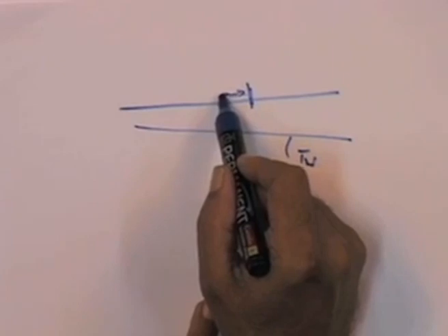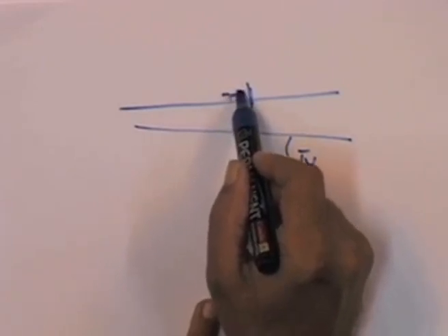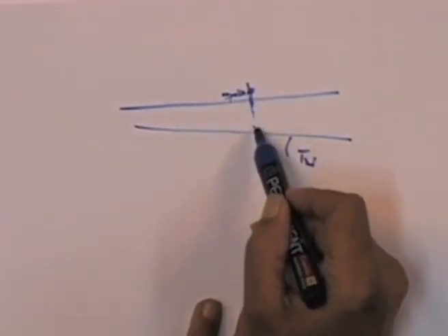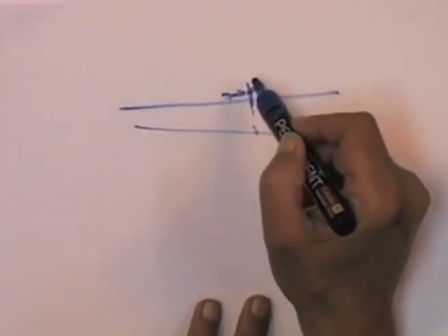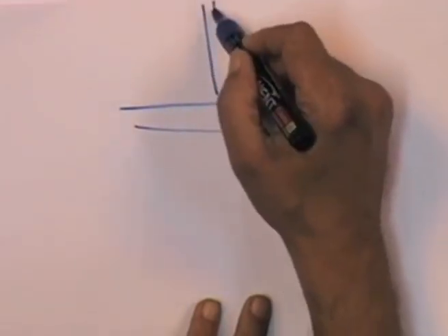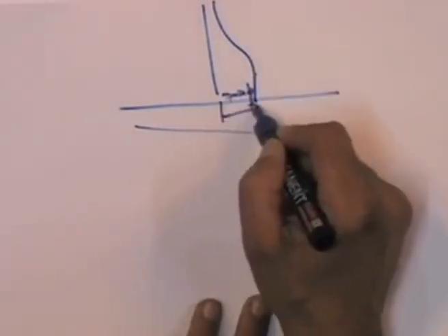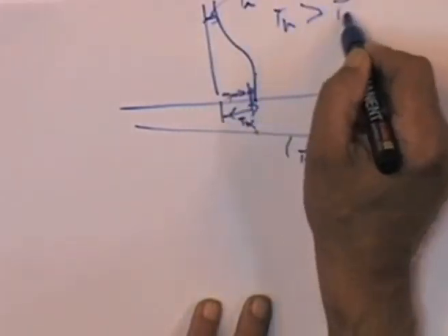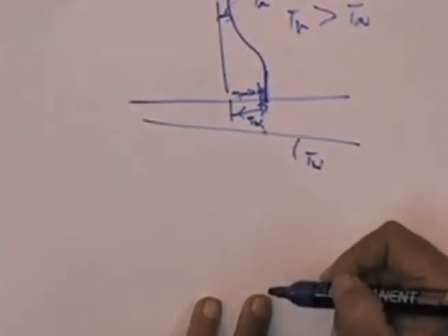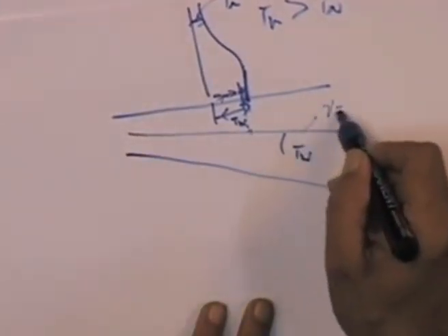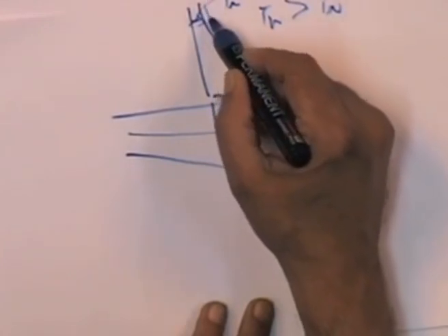much so that the convected heat into the layer, the temperature here could well become absolutely equal to the temperature of the wall at that point. So, in effect I get a situation where I have a profile which will look like that. So, basically although Tw is bigger than T infinity, I could get a situation where it is like that. If the slope is still negative, this corresponds to gamma equal to minus 0.5, I could even get a situation which is like that.